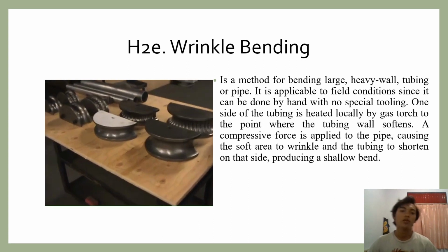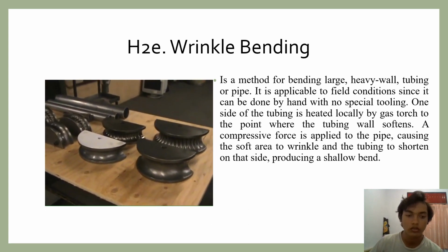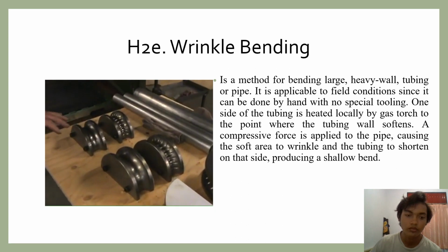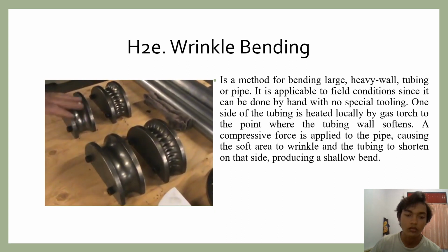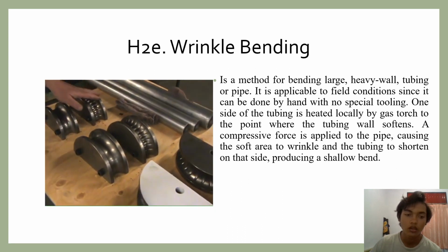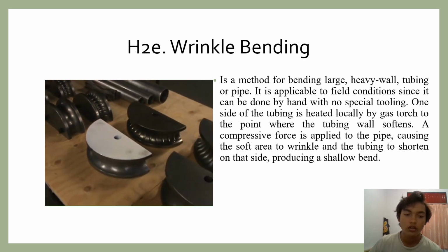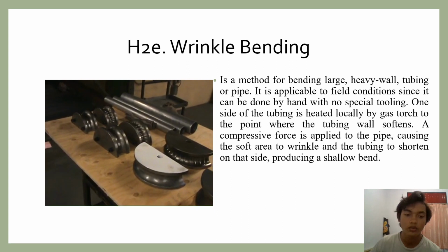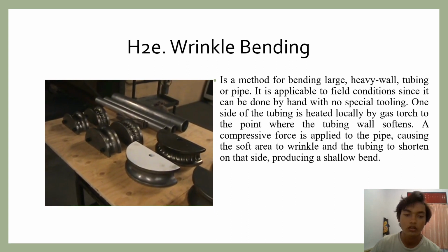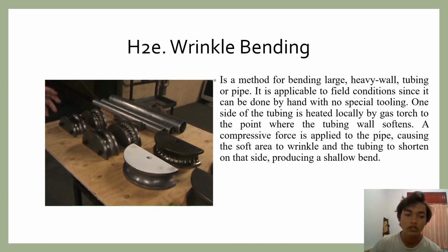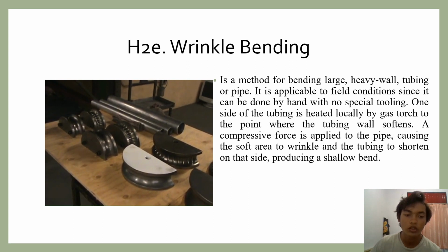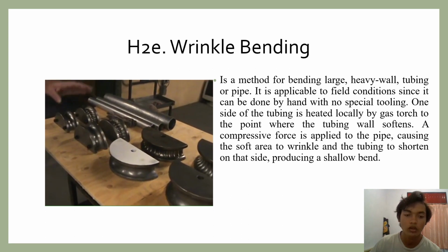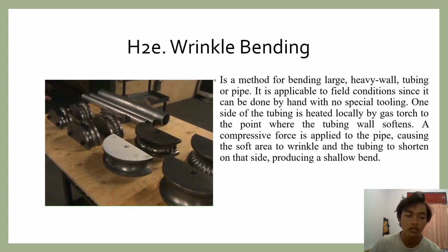Alright, we want to take a minute here. We're going to talk about and show bending on compression benders, the difference between traditional smooth radius dies and wrinkle control dies. The reason for a wrinkle control die is to bend thinner wall material or harder material such as stainless steel. We're going to start by bending with a 5-inch radius, and work our way down into smaller radiuses.